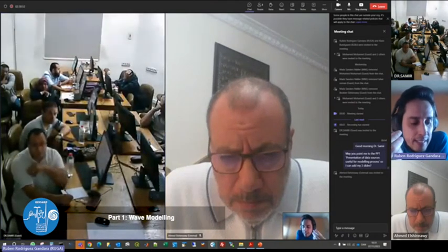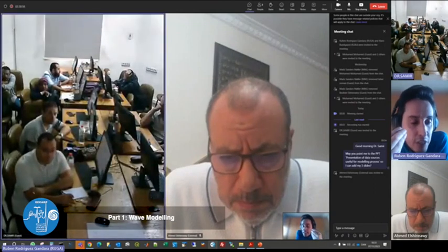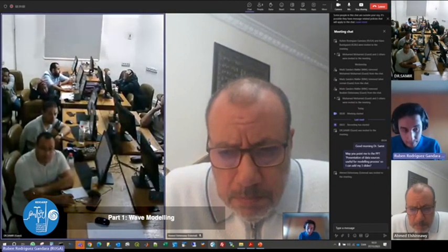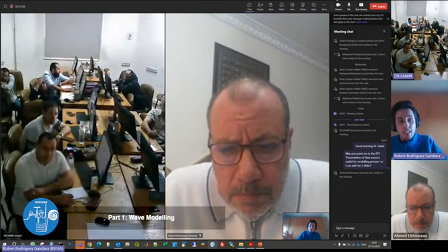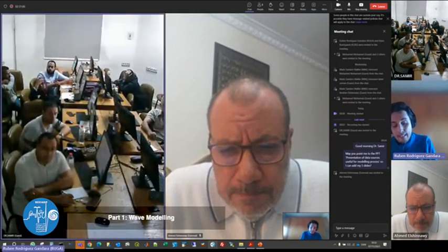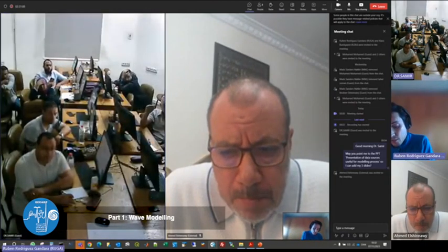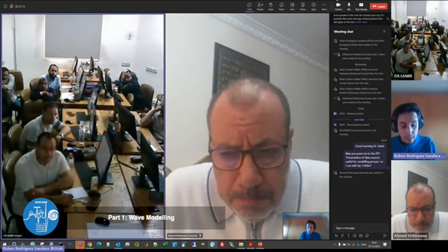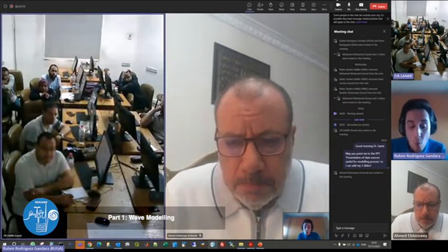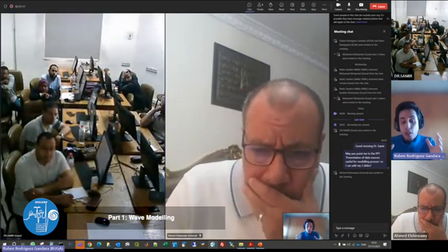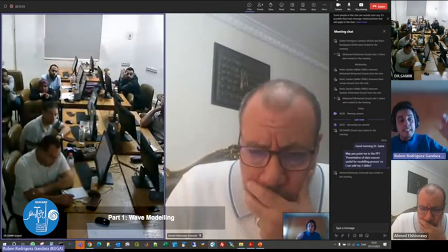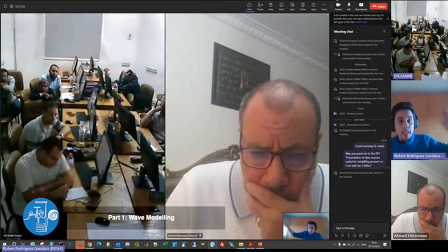The thing is that for the quasi-stationary formulation, as I said before, if you have a small domain and the waves that you are imposing take way less time to travel within the domain than the update of the boundary conditions at the lateral boundary, you can use quasi-stationary, because the computation of each time step or each state will be basically independent of what is happening before and after.